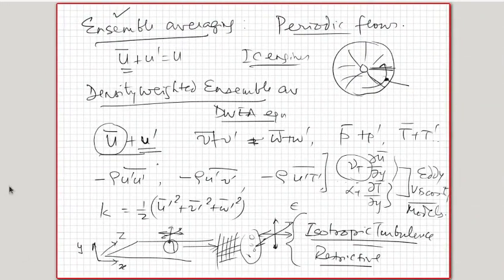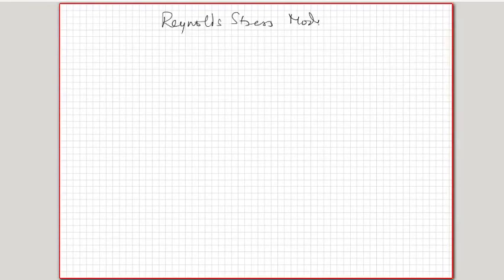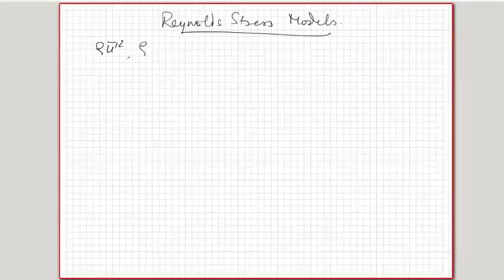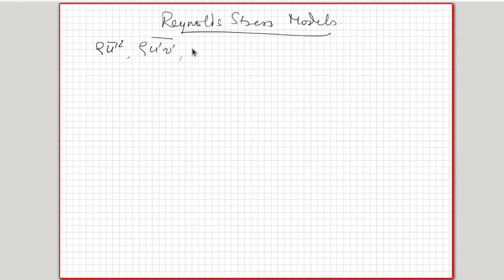So what is more accurate is another kind of models called the Reynolds stress models. So what is the Reynolds stress model? In the Eddy viscosity approach, the Reynolds averaging of equations, for example, if I have a three-dimensional flow, I would be getting 6 quantities: rho u prime square bar, rho u prime v prime bar, rho u prime w prime bar.